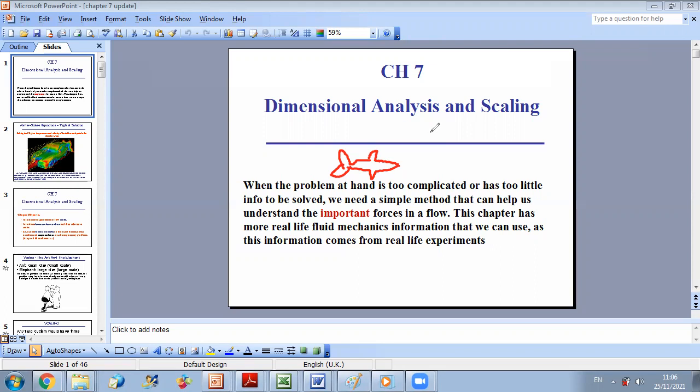And there are many such interesting dimensionless groups that we will go over in this chapter, like the Reynolds number and the Mach number. For example, you are already familiar with the Mach number. We define the Mach number as the ratio of the fluid flow speed over the speed of sound in this fluid. Okay, and we said that this number can help us know if a flow is incompressible or not.